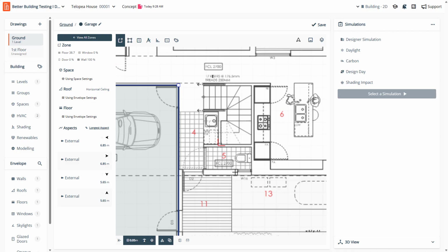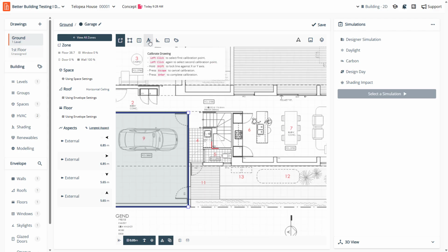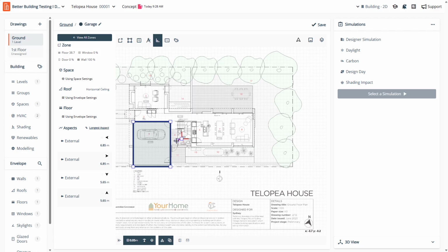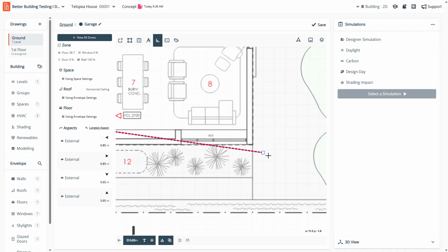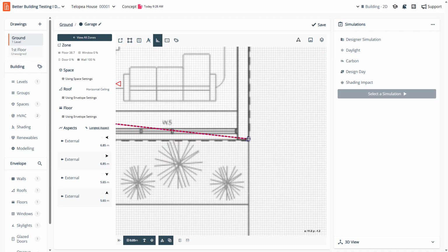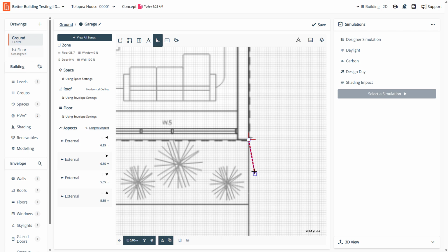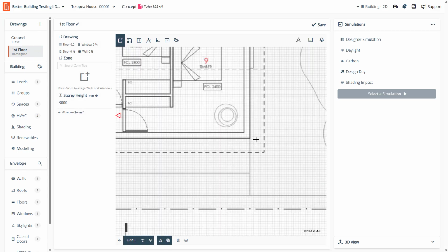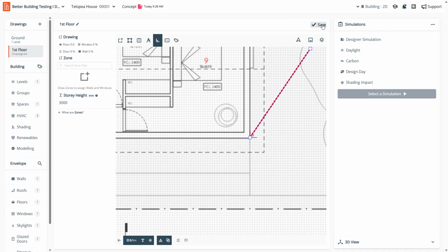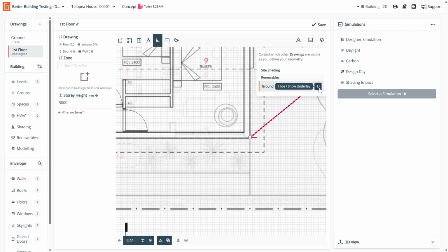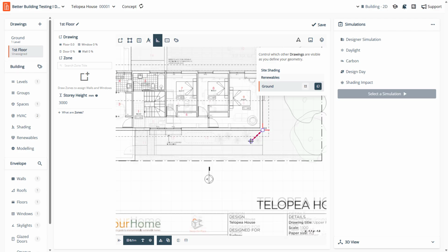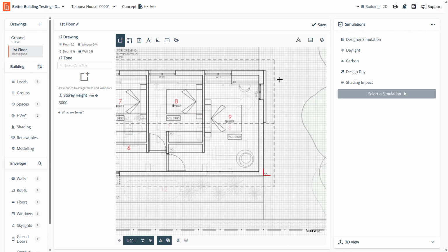You could also use another tool, where we can set the origin. If we set an origin by left clicking set origin, let me start that again, left clicking set origin, and then I've just set the origin at that point there. And then I'm going to do the same over here, set the origin to that point there, and hit save. And what we should be able to do now is see that they're perfectly stacked, one on top of the other.